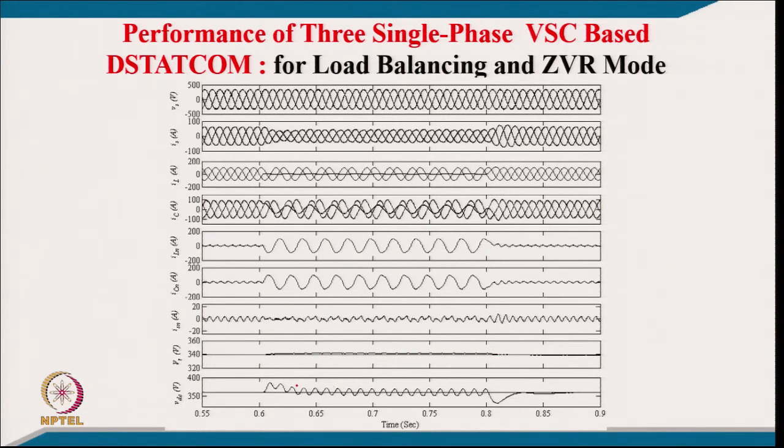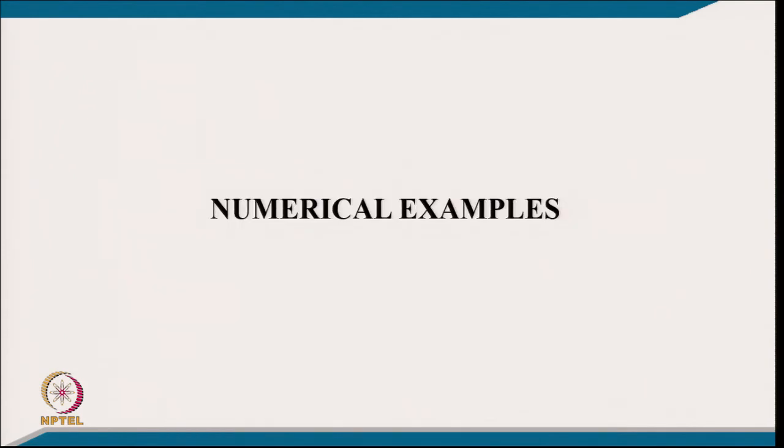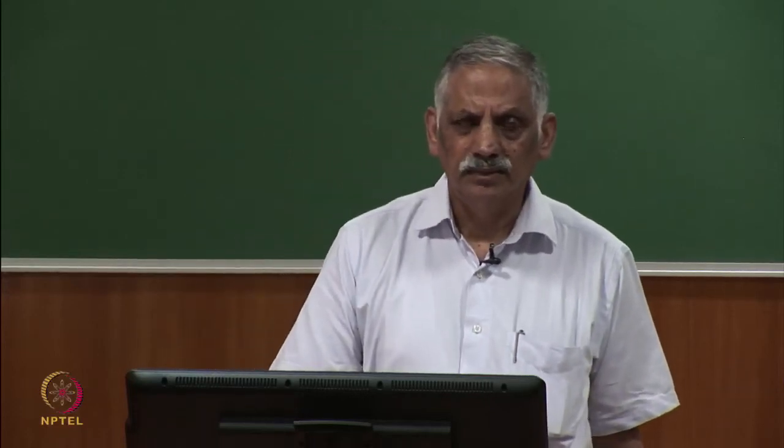And here you can see the DC link voltage again has, apart from that, second harmonics during load unbalancing, and then slight overshoot, undershoot, on removal of the load and application of the load, because the instantaneous energy comes back to the DC link, and here it takes instantaneous energy from the DC link capacitors of the STATCOM. So, with this, these are the case studies we discussed, typically for voltage regulation and power factor correction for 3 wire system and 4 wire system.